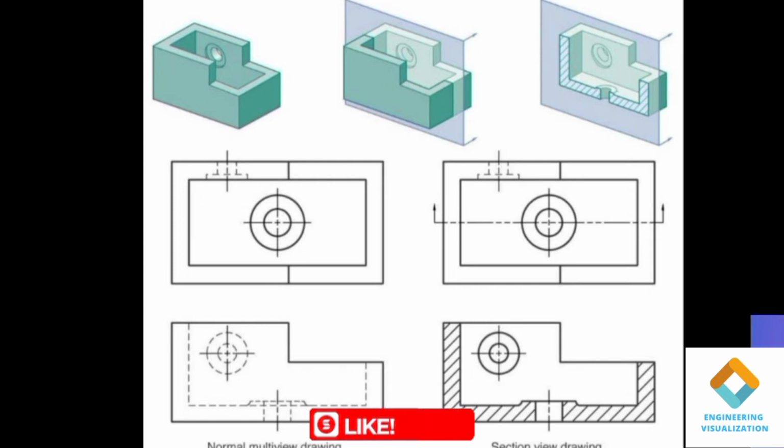So using some imaginary plane, we are going to cut it, both in the horizontal and vertical plane. So by cutting it, you can see in the sectional view drawing, we are able to clearly understand there are two intricate holes. One is located with respect to the bottom face and another with respect to the side face. That is clearly visible in the section view drawing.